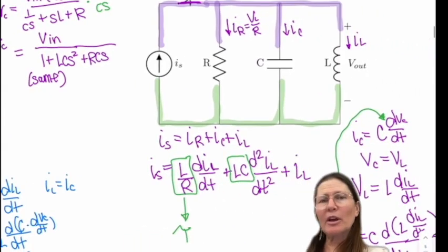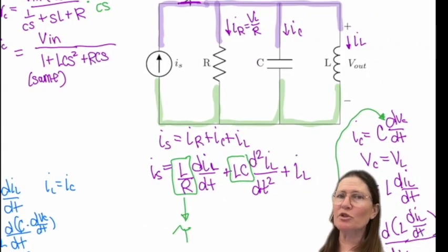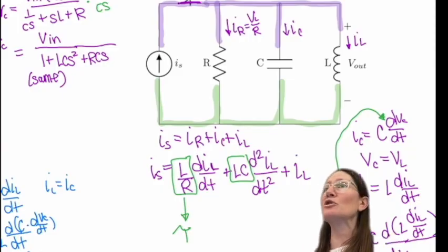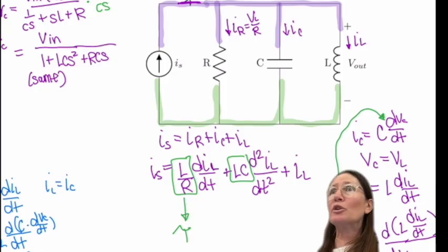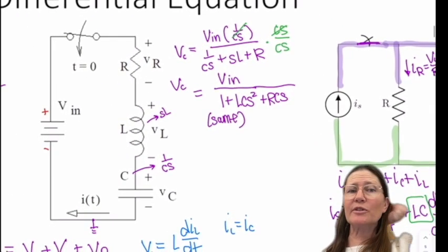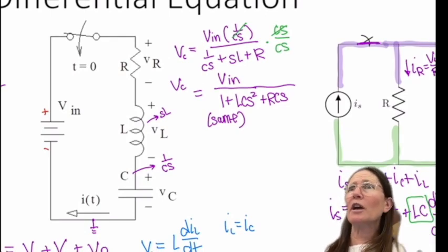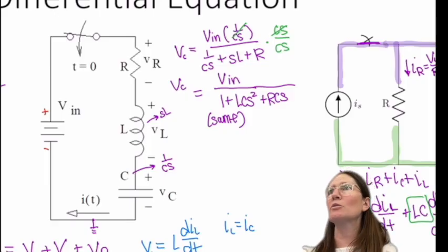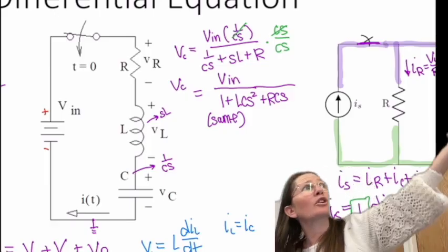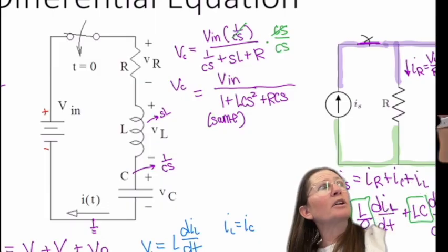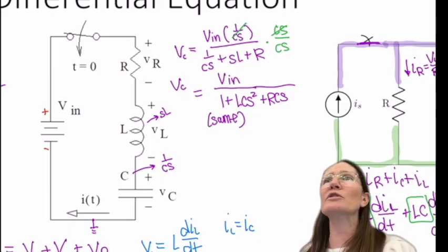And we could do the same thing if we were trying to find any voltage or current within this circuit too. It doesn't just limit it to the voltage across the capacitor. We could find the voltage across the resistor, the voltage across the inductor, the current through there, and it's really an easy way of writing it quickly. So the current here, I of S, is going to be Vn over R plus SL plus 1 over CS.